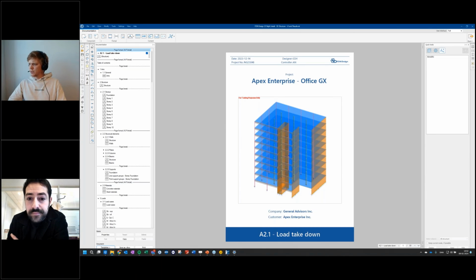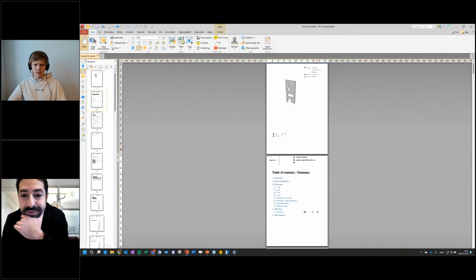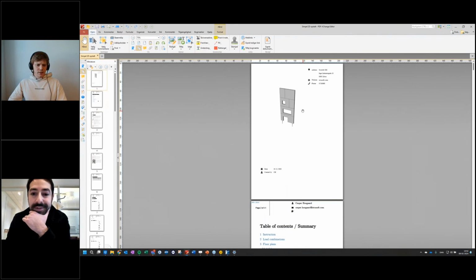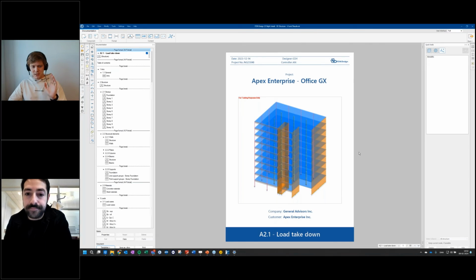Are there more questions you can take in the meantime? Yes, there was one question about the copy paste function into the diaphragm and load setup, and it's about the decimal separator. In your Excel sheet, the decimal separator was a dot, but many use the comma. Will that give an error in the copy and paste in FEM-Design? I don't think so. For me, at least, if it's a cell, you put in value. It doesn't matter if it's dot or comma. At least that's my experience. Only if you put in the coordinates.